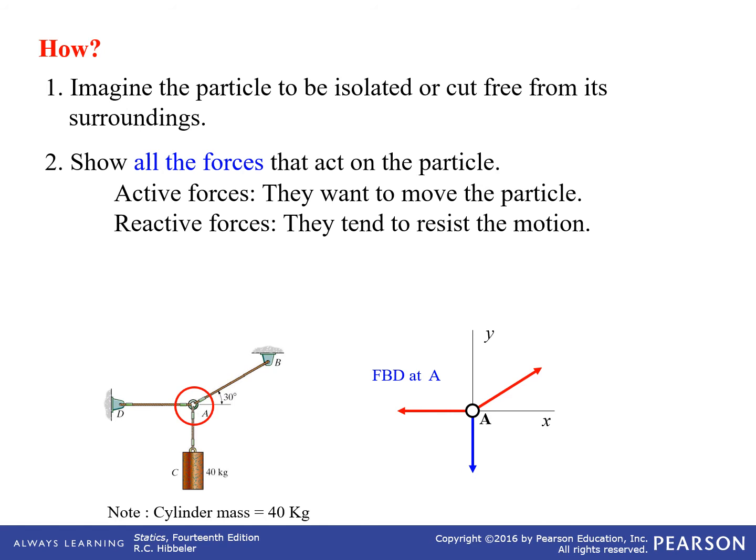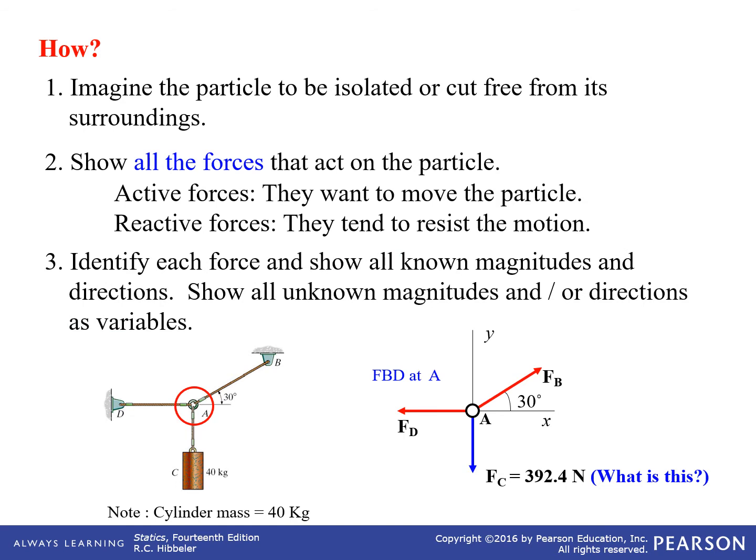What are the active forces that want to move the particle? Well, what's going to move the particle? You've got a weight that's going to act, its gravity, to pull that thing down. The reactive forces are going to be the two cables trying to hold the thing up, and it would be holding it up if it's in static equilibrium.